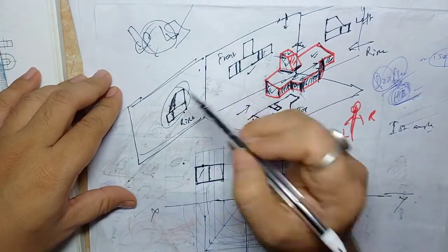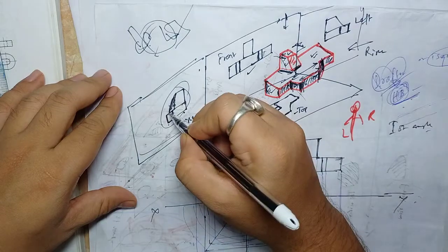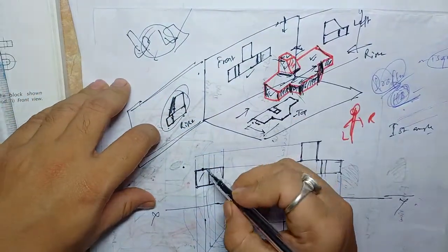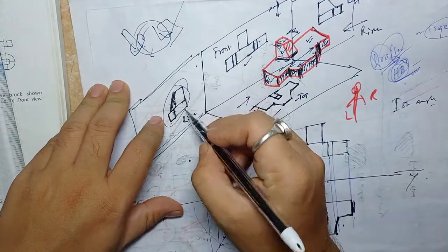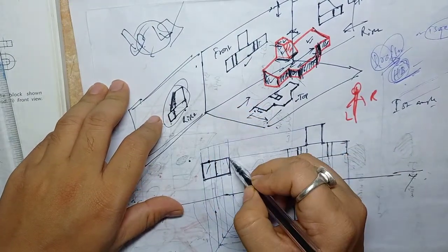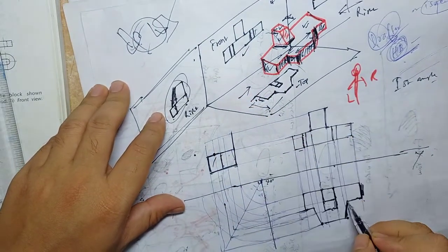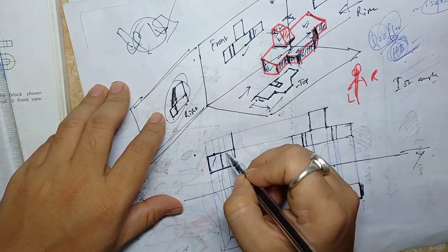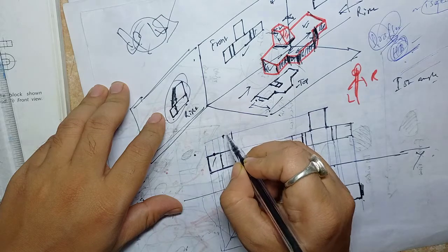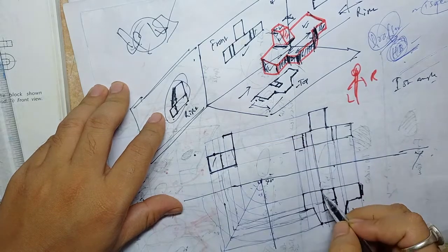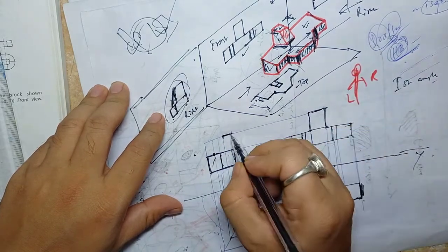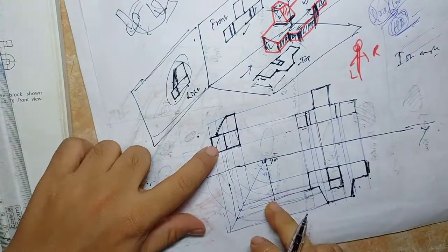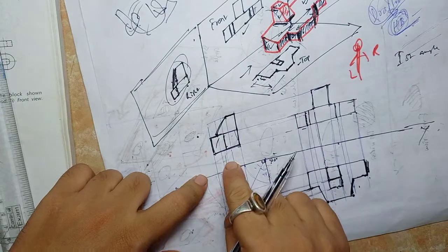You have already drawn a rough diagram. So this is the point where this inclined line will strike, and this edge is up to this point. So draw that edge here. And this edge here is this line, so that edge will come up to this one. This edge here, it is up to here, and then you connect these two lines to get your right side view.